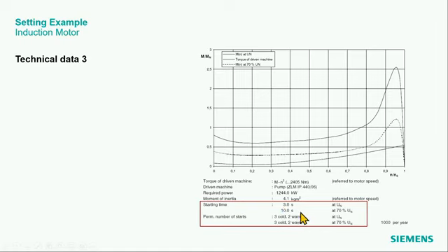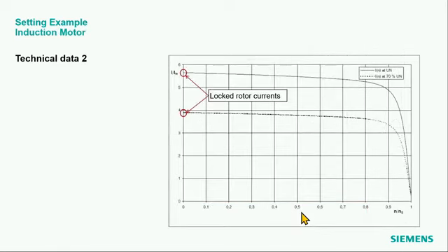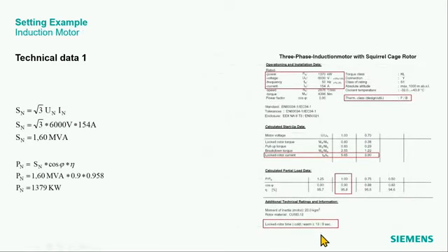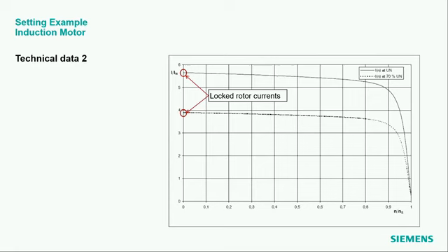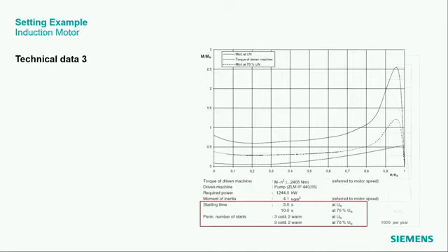If you remember our locked rotor times, we see the locked rotor times are longer than the starting times. That means good. We can use the locked rotor times and we will always be on the safe side. So we don't need a speed meter in that case. It's the first case we discussed before.